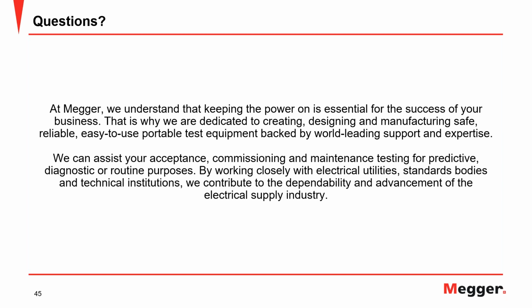So I can only speak with respect to our instruments, and we provide different types of adapters. These come in various shapes and sizes. They can be used on different types of bushings. So we provide these adapters as accessories along with our power factor test sets. Besides that, if you want to do C2 measurements, then we also provide a special adapter, which is basically a banana pin on one end and a little alligator clip on the other end.